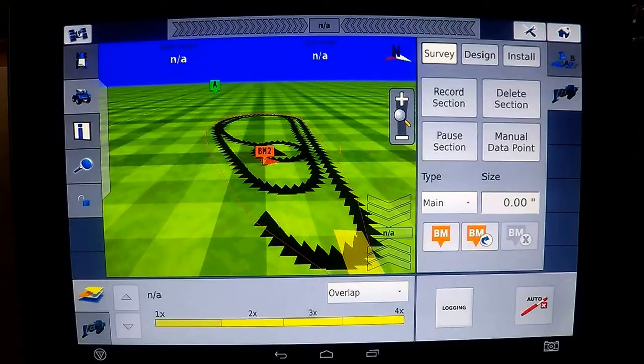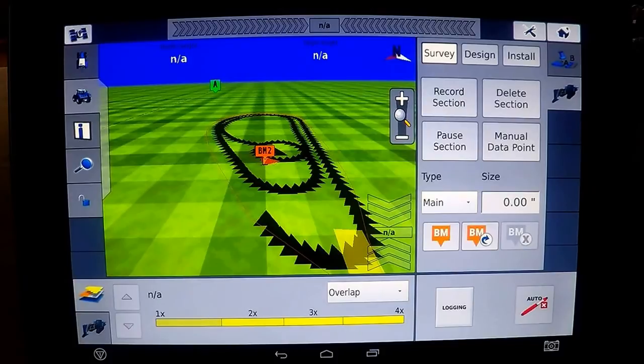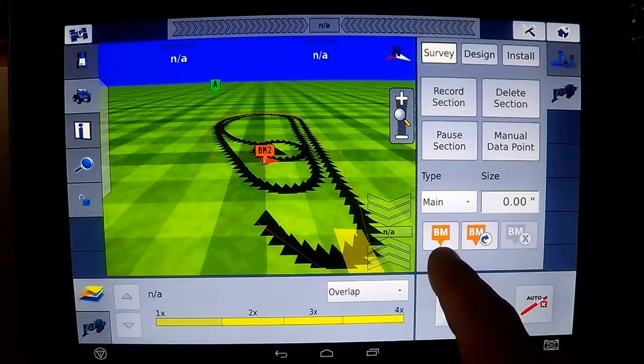Surveying is basically taking a reading every so many feet along a line that measures the altitude at that particular spot very accurately. So what you're going to do first is find a known spot in the field that you can put a disc blade or something down that's going to remain there, that while you're working this particular item you can always go back to.